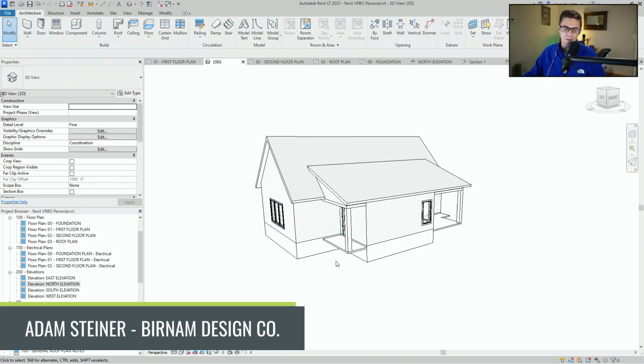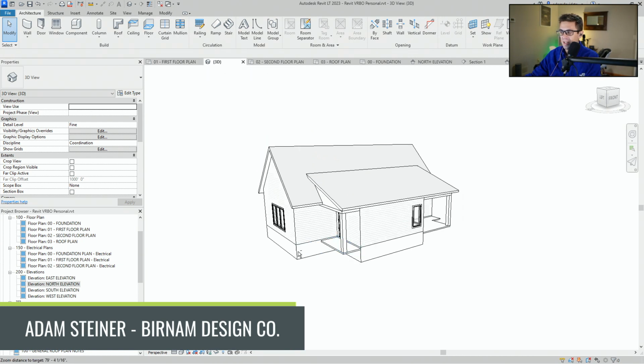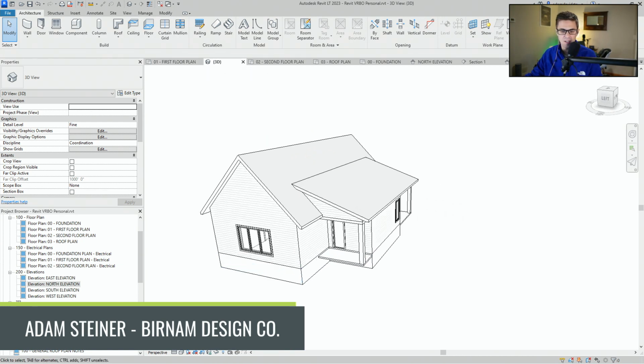Ceilings can be auto-generated. Yeah. I wanted to sketch those just to make sure. Anytime Revit does auto-generation, I feel like you're opening yourself up to stuff being an inch or two in the wrong place because it just grabs the wrong line. Maybe I'm wrong in this, but in my experience, whenever I'm auto-generating floors or roofs or picking lines and picking walls, it gets a little funky on me. So I don't know. What's your experience?